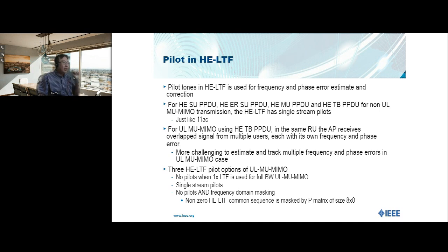In this case, for the same RU, the AP receives overlapping signals from multiple users. Each of them has its own frequency and phase error. So it's much more difficult for the AP to estimate and track multiple frequency and phase errors in MU-MIMO cases.